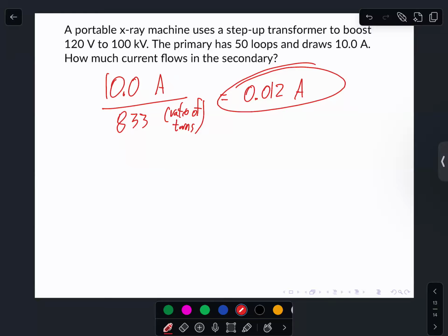If you have 100 turns, you would multiply: 50 volts per turn times 100 turns is 5,000 volts in that whole coil feeling it. Again, that voltage is in both the primary and the secondary, and any coils of wire nearby in that magnetic field.